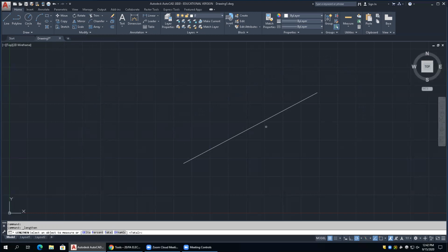So delta allows you to tack a little piece on by adding a delta angle, like say, or a delta distance on this side, or a delta distance on that side. And it's not really adding a piece, it's actually going to shoot it out. So it's actually going to take where the endpoint is and make it bigger. If your delta value is a plus, it adds. If your delta number is a negative, it subtracts.